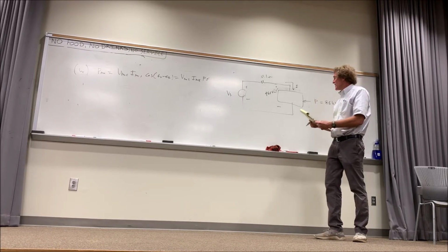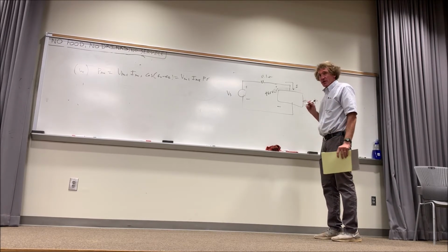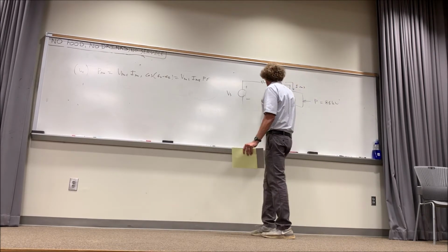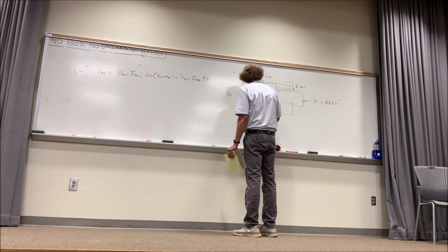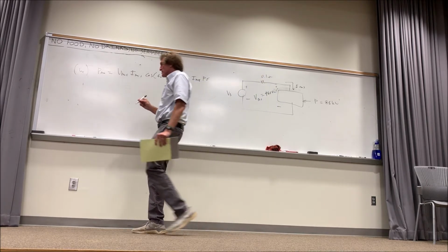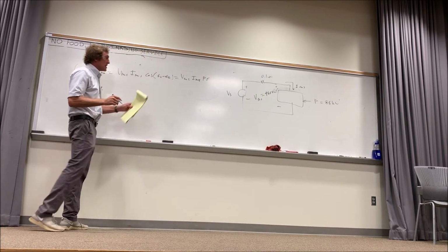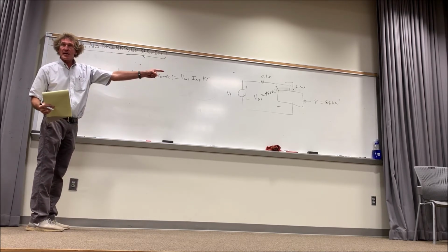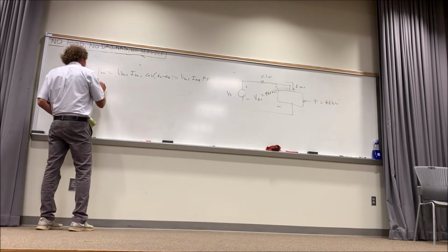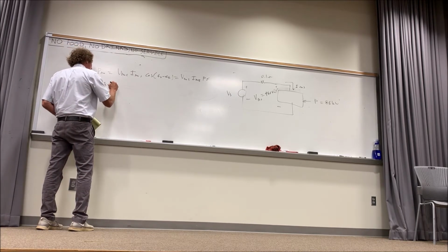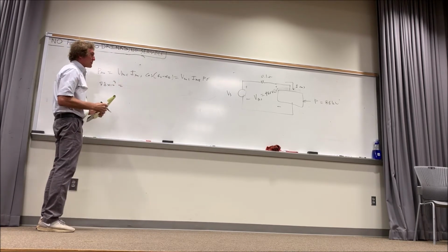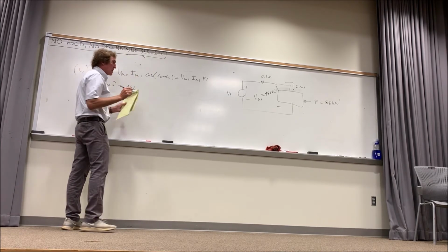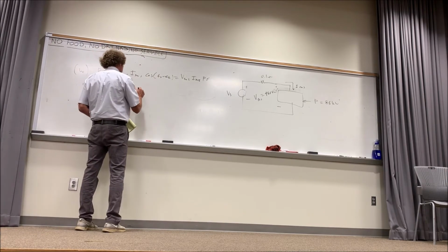Now, when I have that, I want this current, and this is RMS current. So I want the RMS current. This is RMS voltage, by the way. That's VRMS. They always use RMS for power applications. So now I come over to here, and I said, well, I know what the power dissipated is. It's 88 kW. Follow me, class? So I have 88 times 10 to the third watts is equal to VRMS, which is 480. Please watch this. 480, now times IRMS.